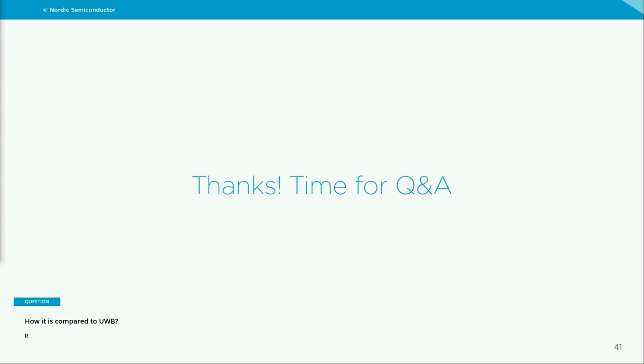The time for fix is shorter with UWB, and the angular accuracy you get out of the UWB is probably also a little bit better. So the key advantage with direction finding on Bluetooth is the power consumption and the cost, because you get a smaller, cheaper device with lower power consumption, while UWB, because of the ultra wide band, has an advantage when it comes to the measurement solution, because it makes it easier to get an angular resolution and to get it faster and more accurate.